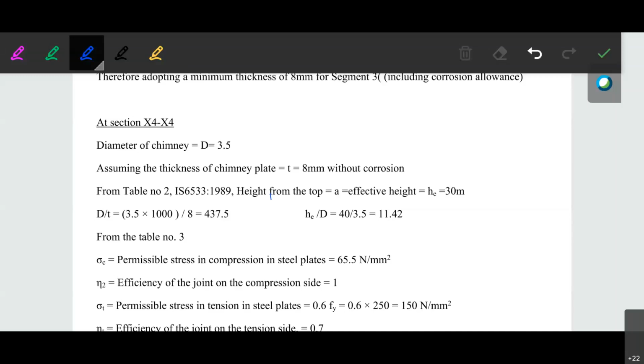Again here we are not converting into mm, rather it should be kept converted in meters. Here you converted Newton per mm and here also you took the value in mm. Okay, we get the value of the thickness T required as 2.51 mm. This is for the tension side. Similarly for the compressive side, same calculation is there.